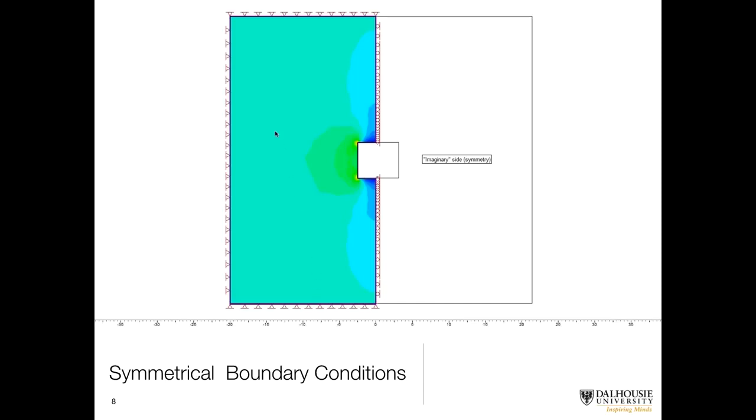That really doesn't have much of an effect on this simulation because they are so far away from the tunnel boundary, an adequate distance, that it doesn't matter if they're fixed or rollers. Now, if I did use rollers over here, again, that would simulate a plane of symmetry as if this tunnel was way over here. And you have to make sure that they're far enough away that there's no tunnel interaction or impact of the boundary conditions on the excavation, unless you intend it to be so, like we have here with this plane of symmetry.